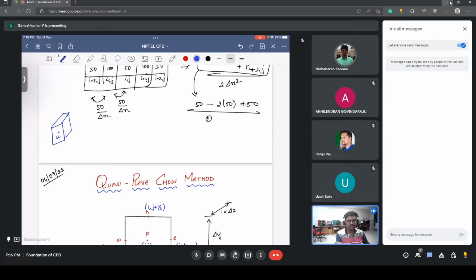Okay, since there is convection in the energy term, you can solve continuity and momentum, get the velocity fields, and based on the velocity fields you can separately solve energy. This doesn't come in a coupled manner. In a simple algorithm, you predict the velocity, predict the pressure, and then correct the velocity. There is no place where the energy equation comes in, because you need not solve the energy equation.